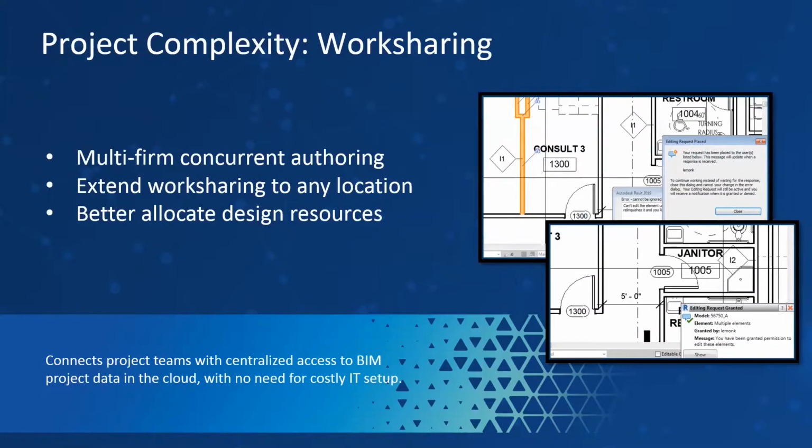Somebody from within that company will have to respond to a particular design issue that's raised. Within collaboration for Revit, we've had work sharing for a long time, which is also being carried through into BIM 360 Design. You can see here, if somebody in the top window wants to move this particular wall and they don't own that wall in their work set, then an editing request will pop up within the Revit window of the person that does own that work set, and they're able to grant access for that user to move or delete the wall. So it helps you manage that design iteration process as tightly or as loosely as you want. You don't always have to have work sets set up whatsoever.